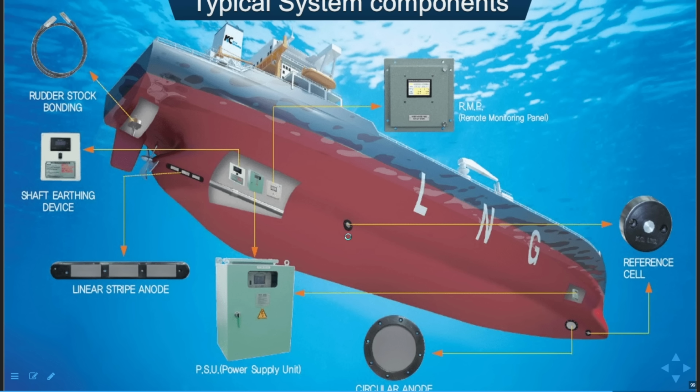So this is what you would probably find in a modern ship, a cathodic protection unit with anti-fouling, as it's called, where a little bit of copper ions never did anything bad to the ship, but marine life it definitely got rid of, or put a permanent end to. So you would not find marine life under the hull of a modern ship, and you would still find that the bottom hull is not corroding, because something else is corroding instead. So we are sacrificing that material to protect the hulls of the ship.